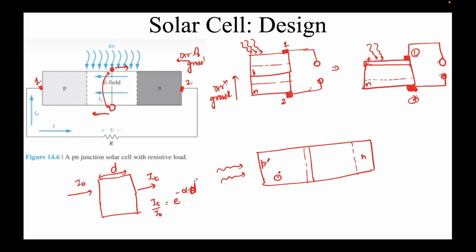That's why I want to make D smaller. You can argue that, okay, choose a material which has smaller alpha. Absolutely, that will work. But in nature we are limited; we need a semiconducting material of a reasonably low alpha, right? And we also want to reduce the thickness T so that the intensity that is reaching... So here starts your depletion region. This is the depletion region. Here IT is reaching here. This is the depletion region.